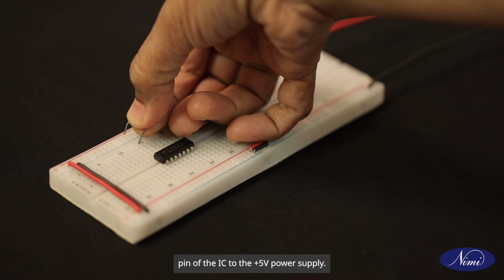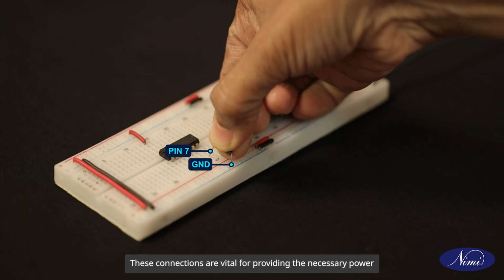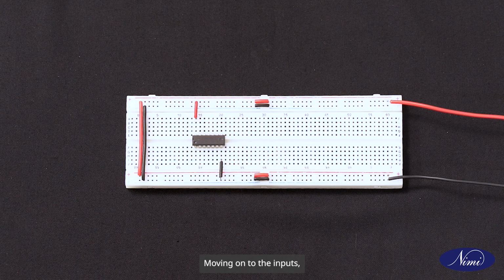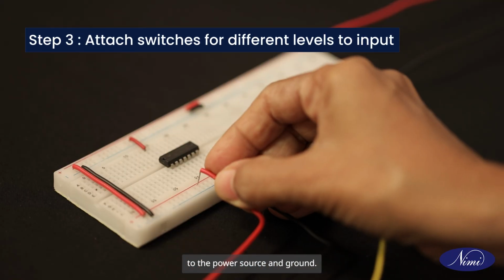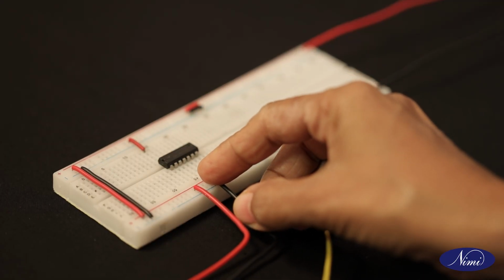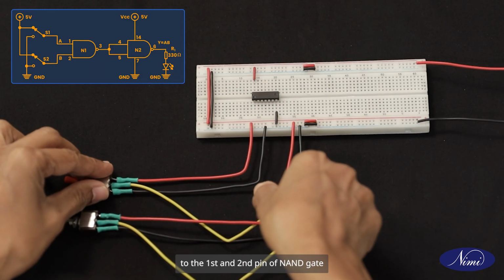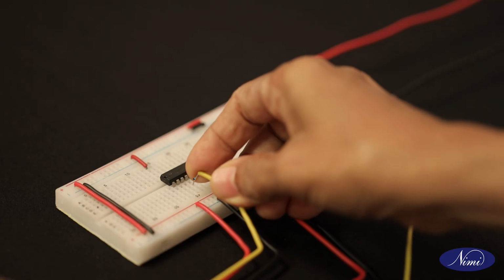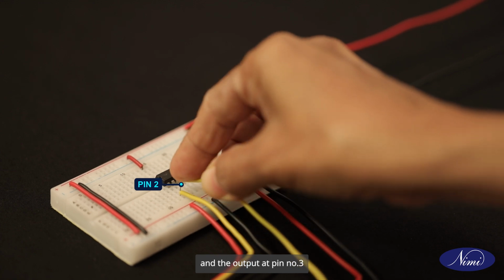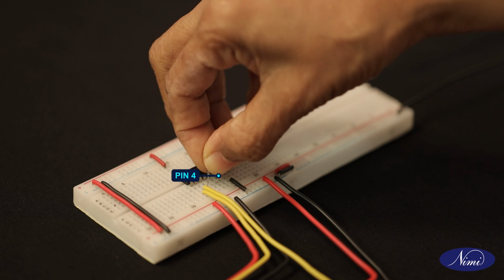Next, connect 14th pin of the IC to the plus 5 volt power supply. Then, make sure pin 7 is connected with the ground. These connections are vital for providing the necessary power and establishing a common reference for the circuit. Moving on to the inputs, connect both terminals of the toggle switches to the power source and ground. And connect switches S1 and S2 to the first and second pin of the NAND gate. And the output at pin number 3 is connected to both 4th and 5th pin of the same IC.